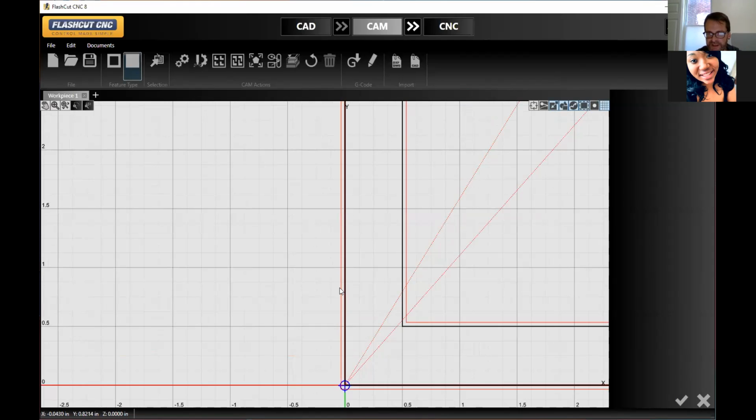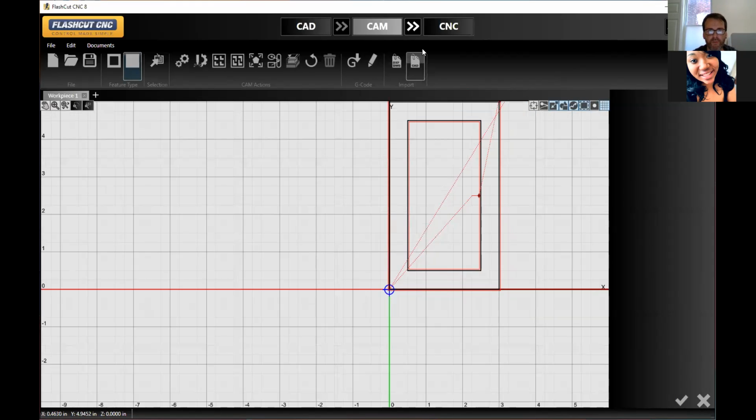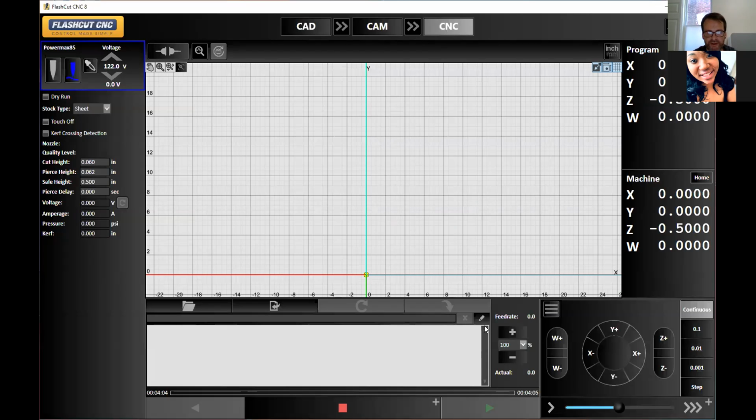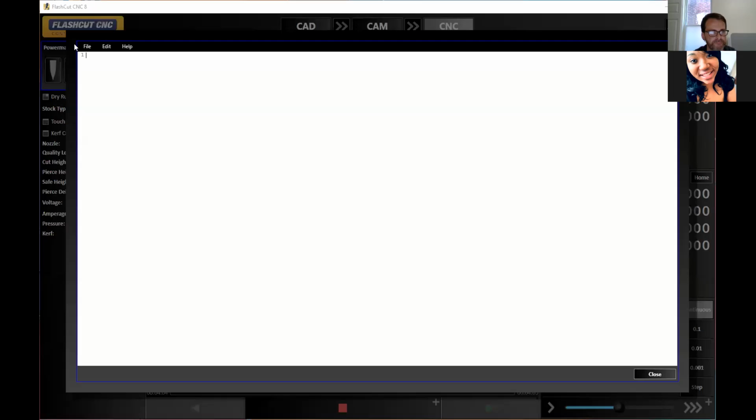And it does that because there's 0.034 inches of burn off when the torch is cutting out your shape. Now that's like a negligible amount. In reality, it's not enough to even worry about. But when we pull this up, we will get an error message.